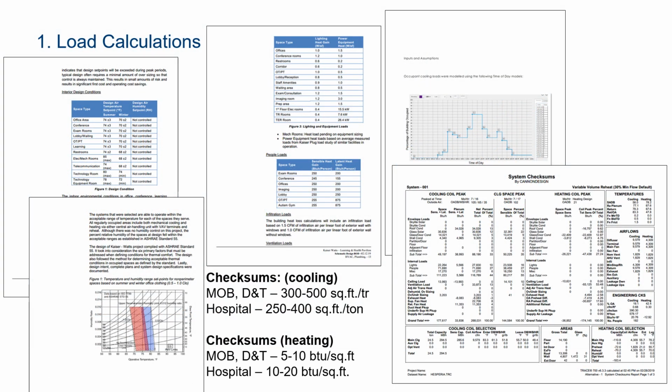Issue number one is that we want to see your load calculations, and we really want to participate in your load calculations. We have some information we can share on internal loads and occupancies and usage factors. We've actually done and published research on plug loads, so we want to participate in those. And we do have expectations. We know what cooling load ranges are supposed to be and what heating load ranges are supposed to be, and we want to talk about systems that fall outside of those ranges.